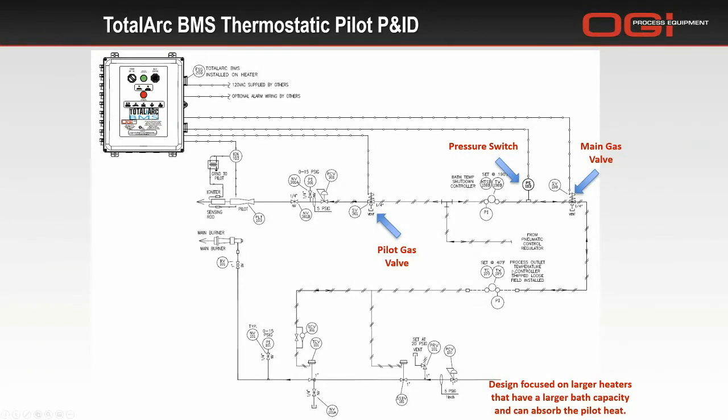One of the drawbacks is that at all times you are going to maintain the pilot valve and the main gas valve on, and that of course draws power out of the system. There shouldn't be a major concern about this, except for systems that are remotely located and run on solar power.